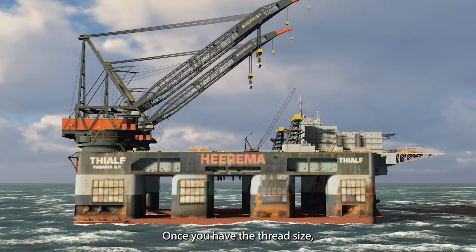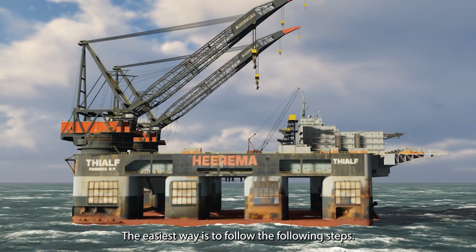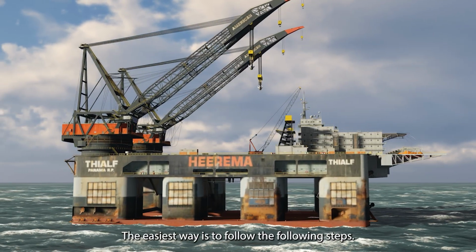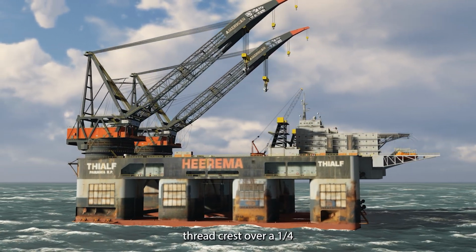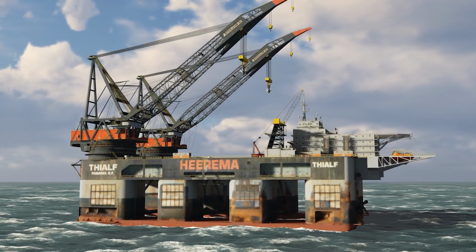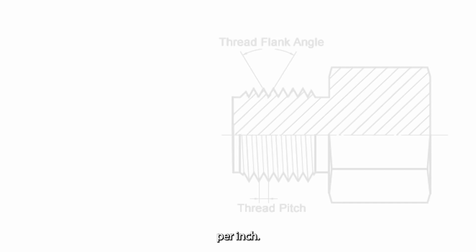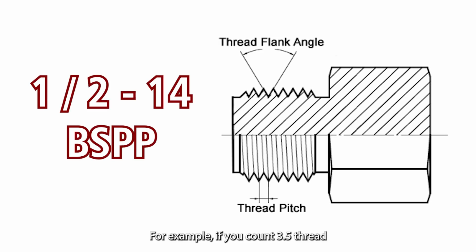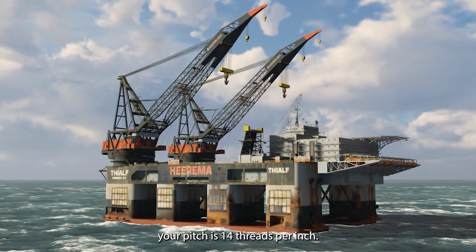Once you have the thread size, it is important to verify the pitch. The easiest way is to follow these steps. Count the number of thread crests over a 1/4 inch. Multiply that number by 4 to get the number of threads per inch. Example, if you count 3.5 thread crests over a 1/4 inch and multiply the 3.5 by 4, your pitch is 14 threads per inch.